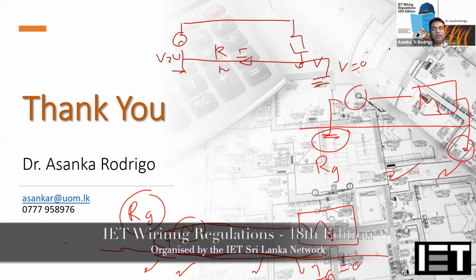But in the front end or upstream, there can be very high fault current. In that case, in order to handle it, you can use either a core balance transformer or certain CTs with an EFR for those locations. So you don't need to worry about your fault current. The only thing is, you have to size your cables to handle that fault current, and if the protective device can detect that fault current, then that is it.